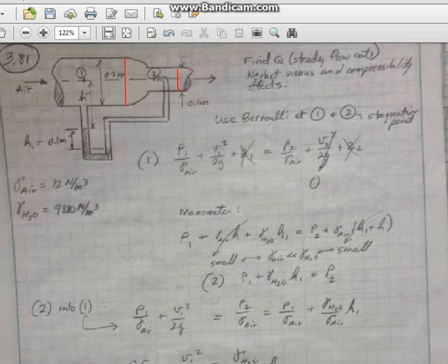little diameter. So there's going to be a constriction here, so velocity is going to increase, as you see from homework number 1, where you have that tube that's decreasing in diameter. The air is coming in the big end, and it's hitting this pitot right here. And so that's going to be a stagnation point, right? And so basically we're using this pitot tube to change the velocity into a pressure, and that pressure will show up as this differential in the manometer here. So a little bit of manometer in here as well.